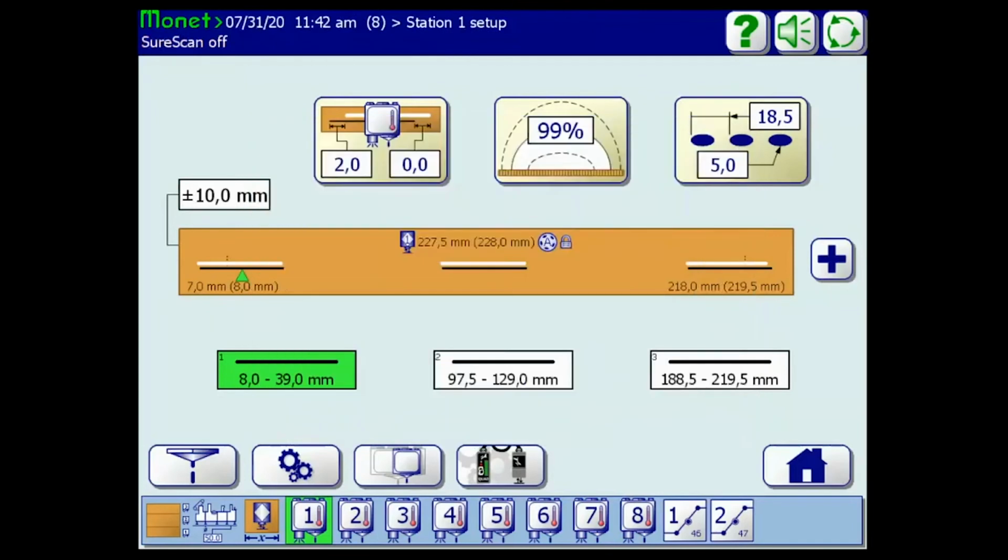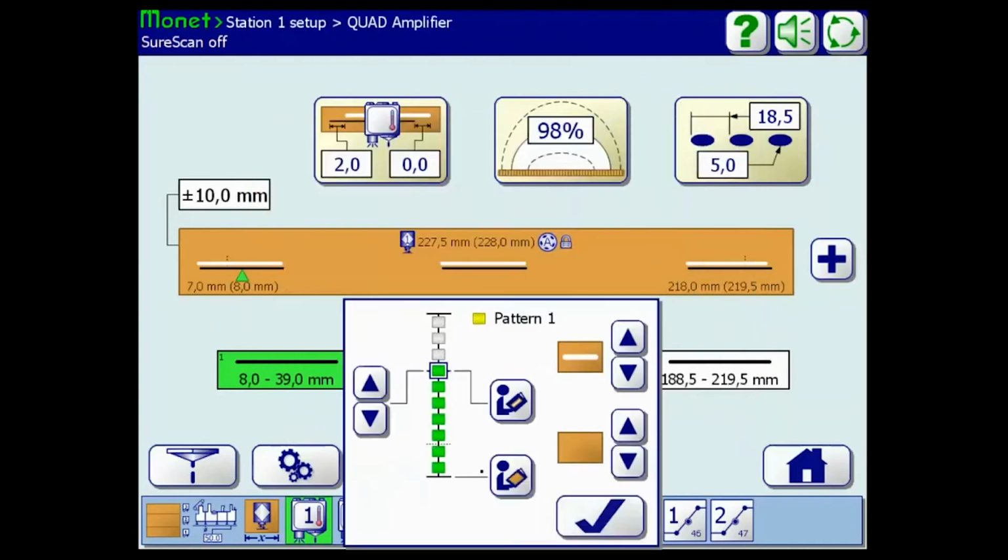So ideally, when we set up this detection sensor, there's a sequence that's best, a rule of thumb to follow. With no glue underneath the sensor, we should see no LEDs. It's pretty much that simple. If we ever see any LEDs on this menu or on the corresponding amplifier with no glue underneath it, we would want to relearn the background, okay?